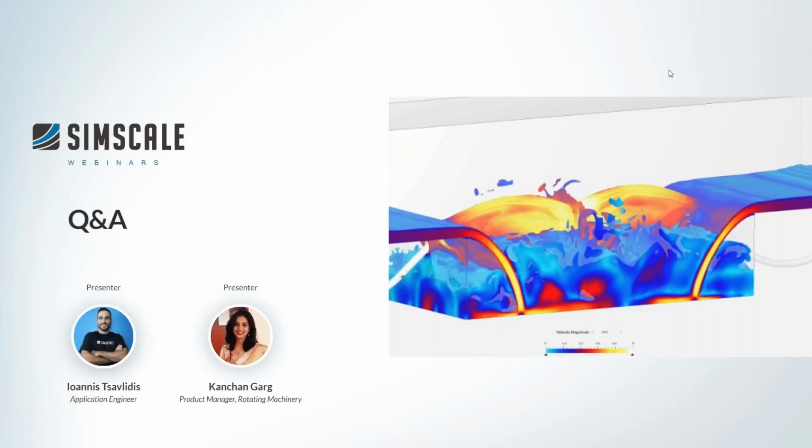All right. So there was a question about how the meshing technology for this new multiphase differs from Snappy Hex or that of the other commercial software, and I'll take that, Jonas. So as I mentioned in my presentation, at the back end, this is a binary tree based mesher.